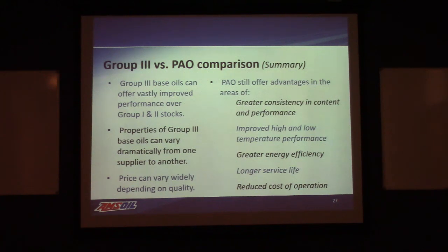PAOs still have advantages over the Group 3s: greater consistency in content and performance, expanded high and low temperature protection, greater energy efficiency, better fuel economies, what we're talking about there. If you can control wear better, you're going to have longer equipment life. If you can control oxidation better, you're going to have longer service life of the oil. And PAOs do have a greater ability to reduce the overall cost of operation of a piece of equipment than the Group 3s do.